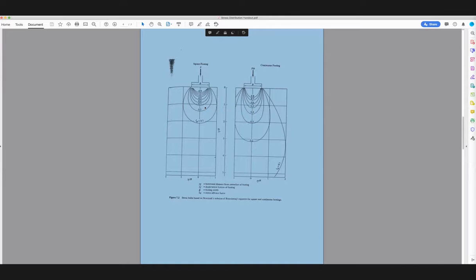I would say probably 2 decimals is all you're going to be able to wring out of this kind of graphic for precision on your influence factor. But that shows you very quickly what the number is, what your stress would be at a given location, and it brings in, importantly, the ability to move around to different locations under the footing, meaning corner or side versus center and so on. That kind of thing gets accounted for with this graphic.